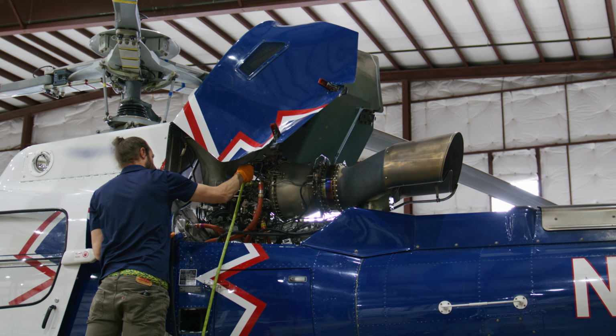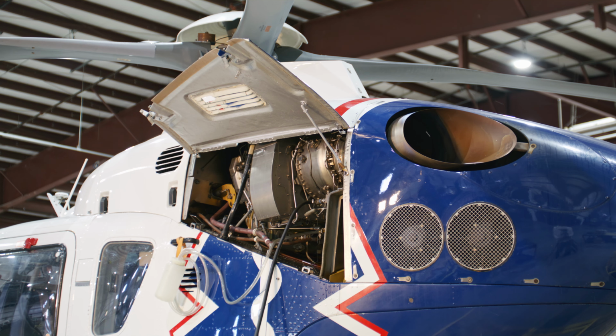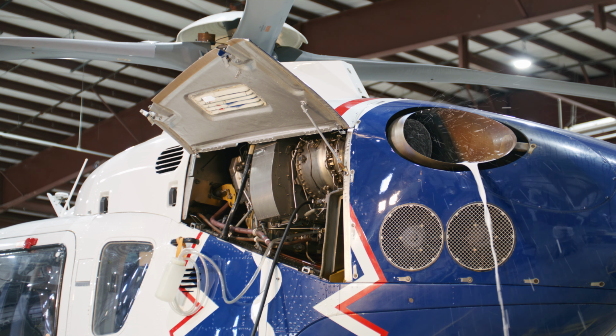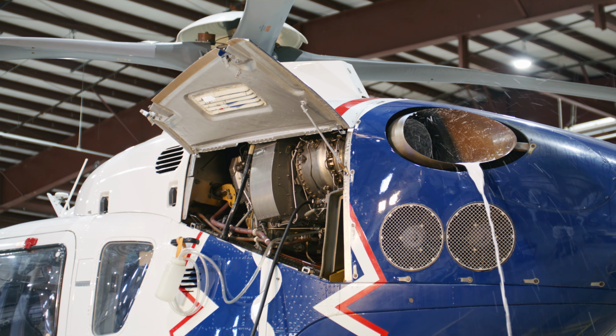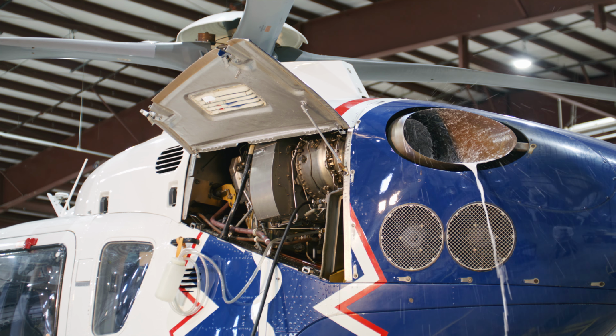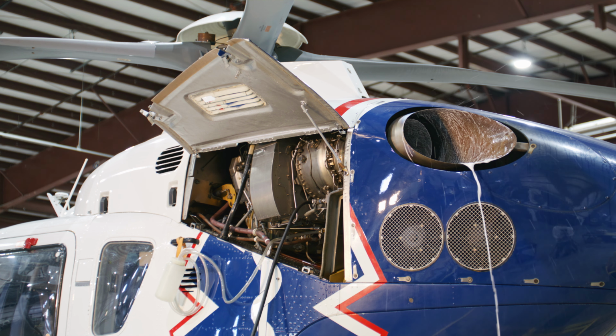Delivery of a liquid at a rate higher than specified can cause damage to the engine. A slightly lower rate is not harmful, but keep in mind that additional ventilations will be required in order to admit the specified volumes. A lower concentration, volume, or abbreviated soak time will not adequately remove contamination.